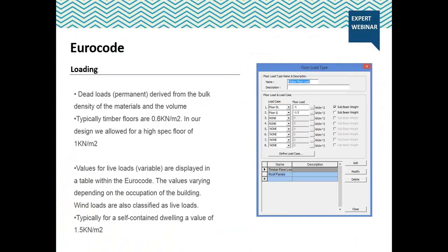For the scale and location of the EC1 project, dead loads, live loads, and wind loads were modeled on the structure. These loads are then applied to the structure and adequacy checks are then made. Ultimate limit state assesses the strength of the structure and ensures that the structure does not fail under ultimate forces and moments. For these checks, factors are applied to the load.